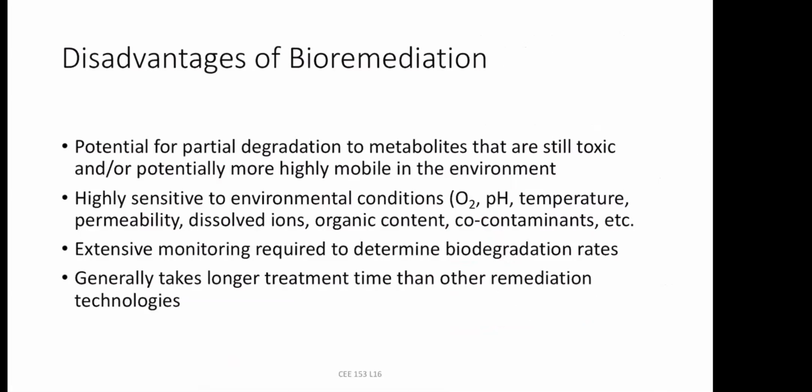So the disadvantage of bioremediation is it takes a long time. It is very sensitive because it relies on microorganisms to degrade the contaminant. It depends on oxygen, pH, temperature, all those factors. So it's a very controlled environment, and you have to really have those in place to be efficient. You need to monitor it because sometimes if the microorganisms are dying, you really don't have any degradation. That's why in places where you have an emergency need, you don't use bioremediation. Anywhere you can leave it for 5 to 10 years, you can use bioremediation because it's cheaper, since you don't really pump. There is no active part.